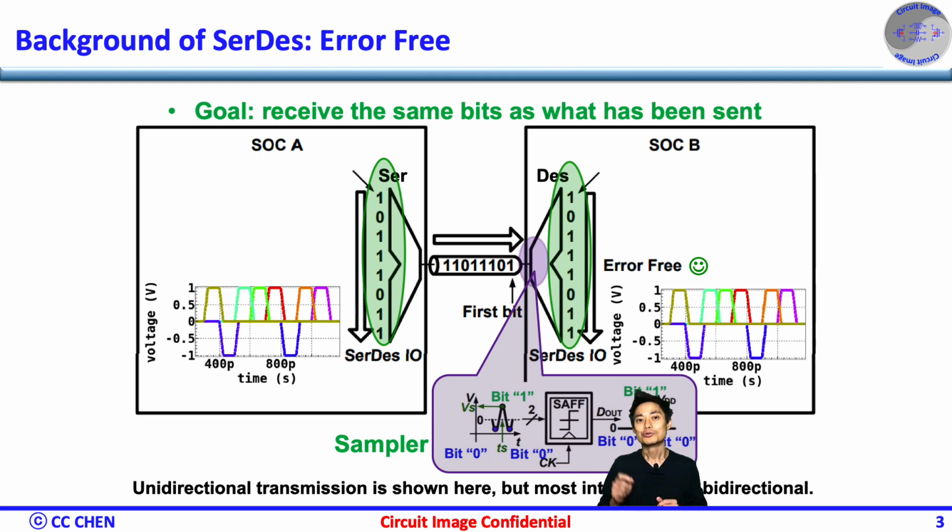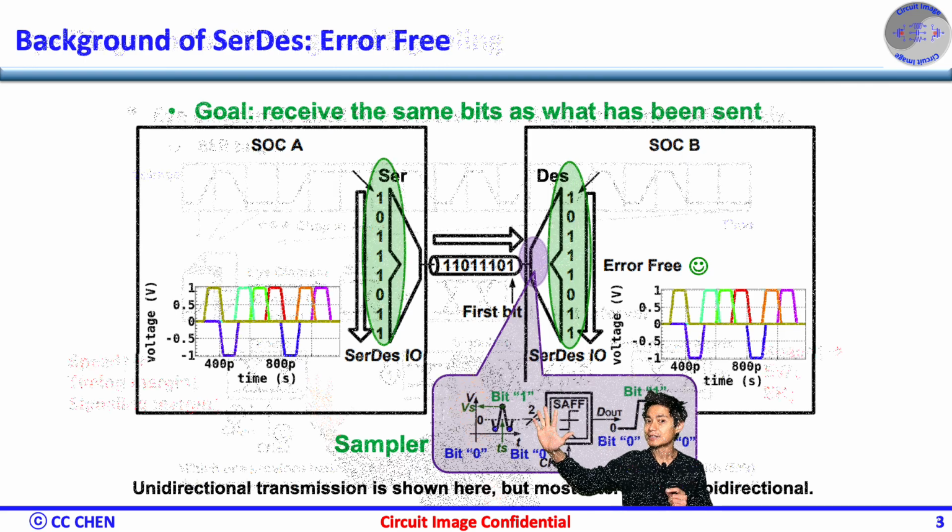That was the reason we mentioned the sampler is the heart of the receiver, which must sit at the RX front end operating at the maximum speed of the serial data rate, before downsampling to the parallel data. Do you have any idea why the speed would make it difficult for the sampler to make the right decision? Think about the timing and signaling images for 5 seconds.